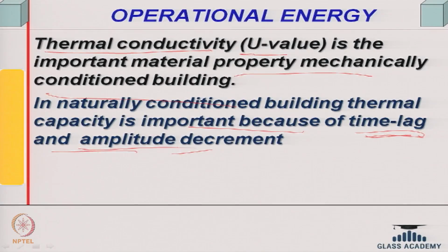So, it takes some time, because a storage element holds the energy and then releases it. There is a time gap between its receiving the heat and transmitting it inside, and when you deal with it mathematically for a periodic wave, you can define something like time lag, phase lag, etc. If it is periodic heat flow, then it has an amplitude, and there is something called decrement in amplitude. This is related to the amount of heat that is stored, because thermal capacity is there, and the amount of heat that can be stored and released later governs this part of it.